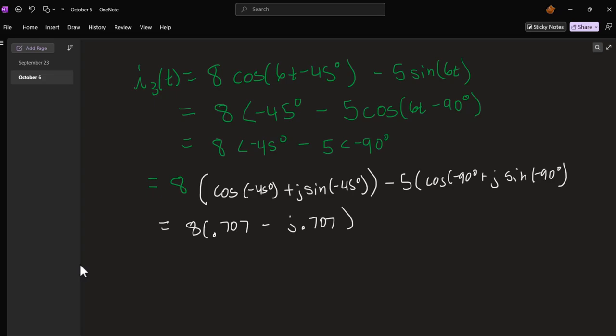So if I want the current through the capacitor, IC will equal 0.012 angle 60 degrees times minus J 15.9 over 20 minus J 15.9.